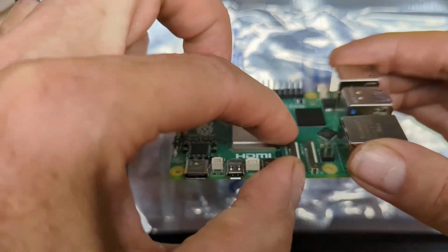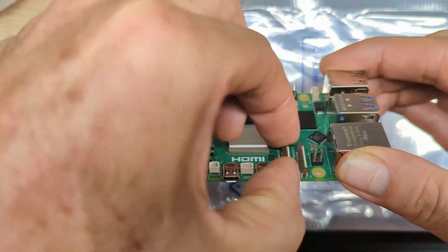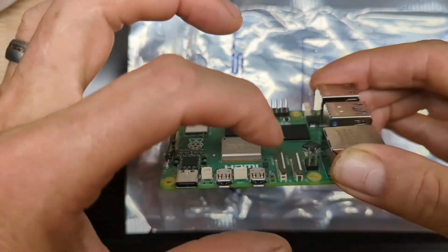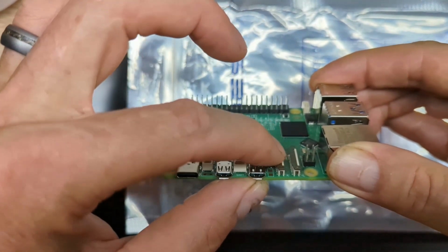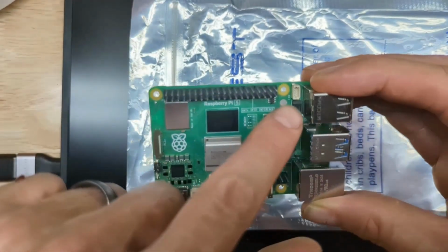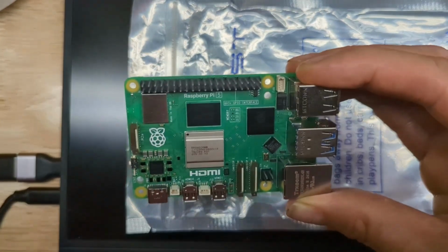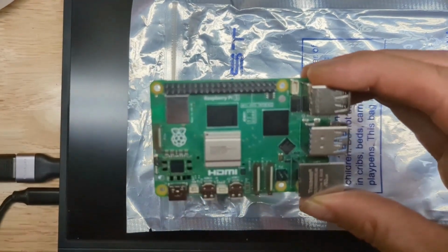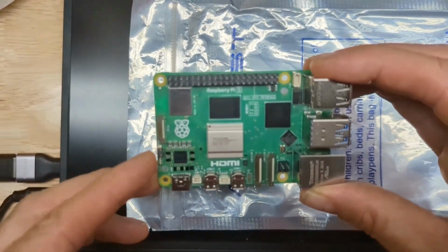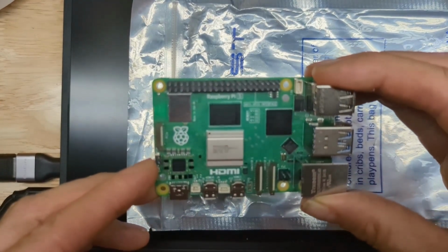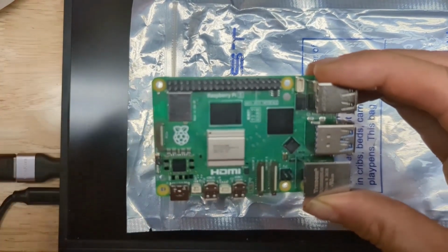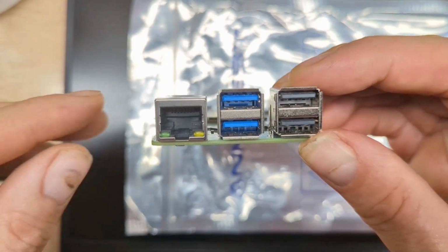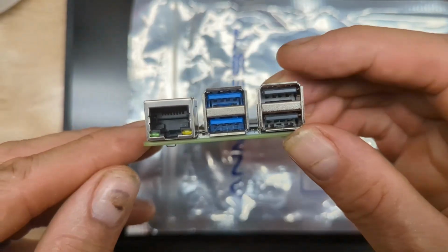Now, these little ribbon connectors, this is where your Pi Cam HQ with a ribbon connector would slide into. Basically, the ribbon would fit down into the slot, and you would push the little tab down to lock it into place to keep the ribbon from disconnecting. And this little white port, this is your power port for the onboard fan. The row of pins is your I/O ports. This allows you to control different sensors like humidity, temperature. You could also control on-off switches for different fans, things like that. And then on the end, we have an RJ45, your standard network cable connection. And then we have several USB ports. You have USB 3.0 and 2.0.